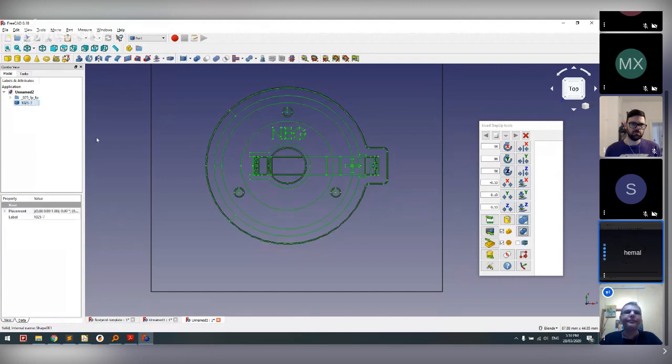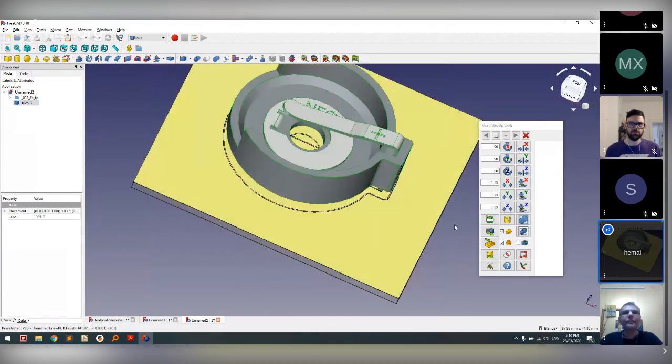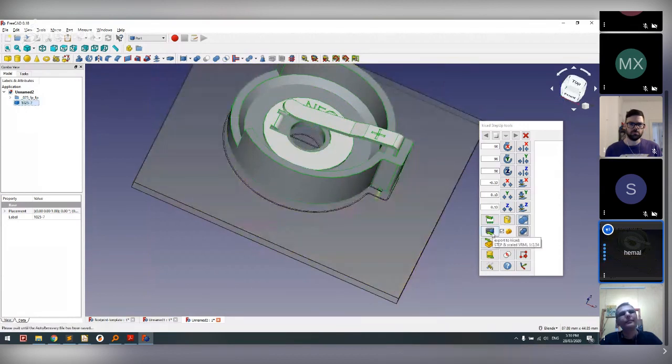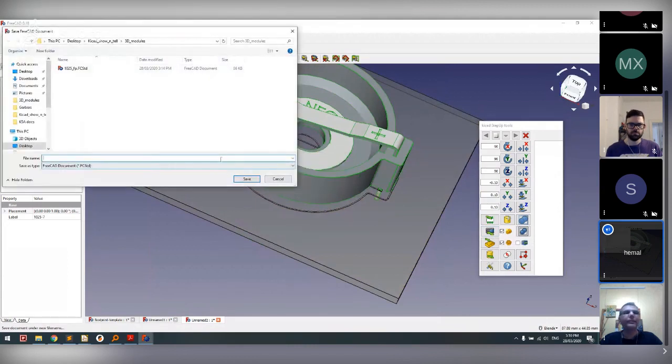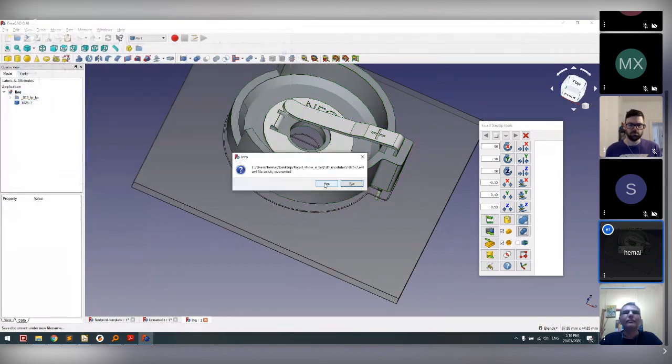Let's go back in the flat lines mode, and we select this and we export the STEP file and the VRML. Sometimes it asks me to save the file. When I don't, my KiCad hangs up, so I usually save it. It's just a good idea to save it, and then you can delete it later on. It says the file already exists, so I'm going to rewrite it.